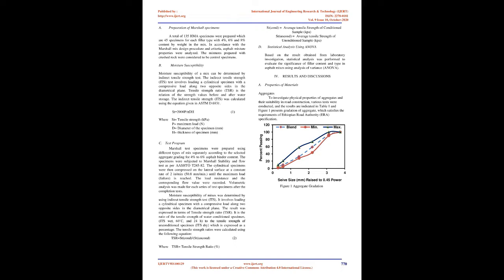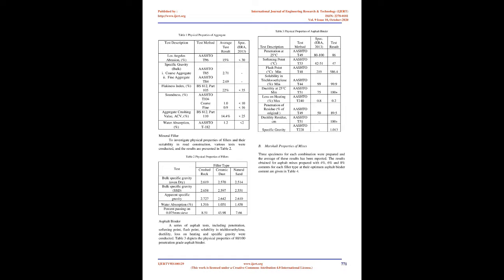21. Moisture susceptibility of hot mix asphalt. Premature failure may result due to stripping when critical environmental conditions act together with poor and/or incompatible materials and traffic. Moisture susceptibility is a problem that typically leads to the stripping of the asphalt binder from the aggregate, and this stripping makes an asphalt concrete mixture ravel and disintegrate. Moisture damage can occur due to three main mechanisms: loss of cohesion of the asphalt film, failure of the adhesion between the aggregate particles and the asphalt film, and degradation of aggregate particles due to freezing.